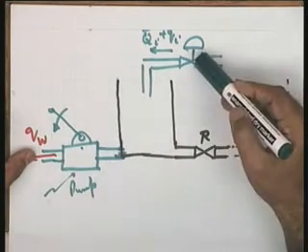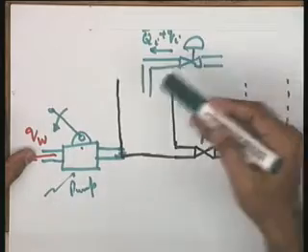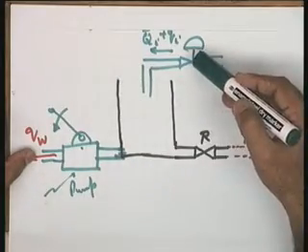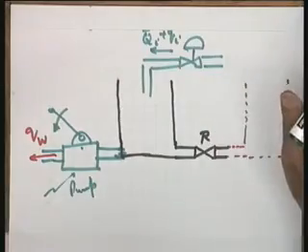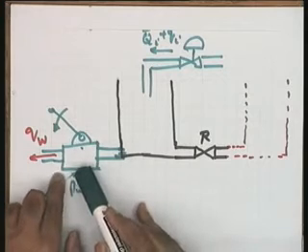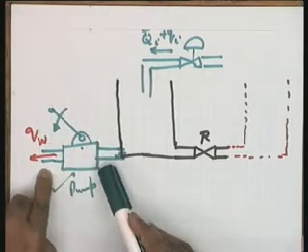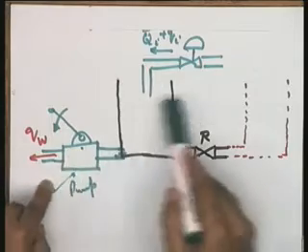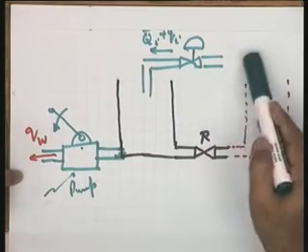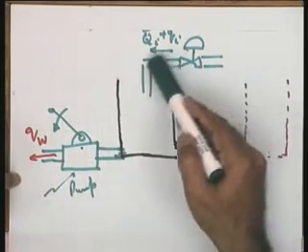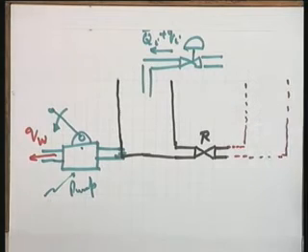So that is why I am taking a different provision over here, that to control the variable I am controlling this flow opening. There is absolutely no problem. If this type of requirement would not have been there, then you could have used the manipulation at this particular point to control the liquid in the tank. In that particular case, you could have given a constant flow rate here. This is one configuration, because control configuration is not unique. I hope all of you are getting it. The control configuration for a system is not unique.